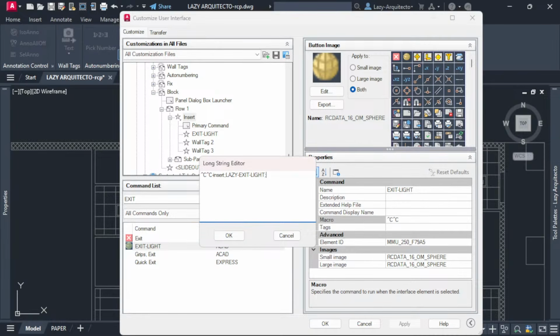So to give me a pause to click on the screen, I'm gonna do that with this / character. Okay, so after that, AutoCAD is gonna ask for the scale of the block. I'm gonna accept with enter for now for the scale that AutoCAD is gonna give me, which is 1.